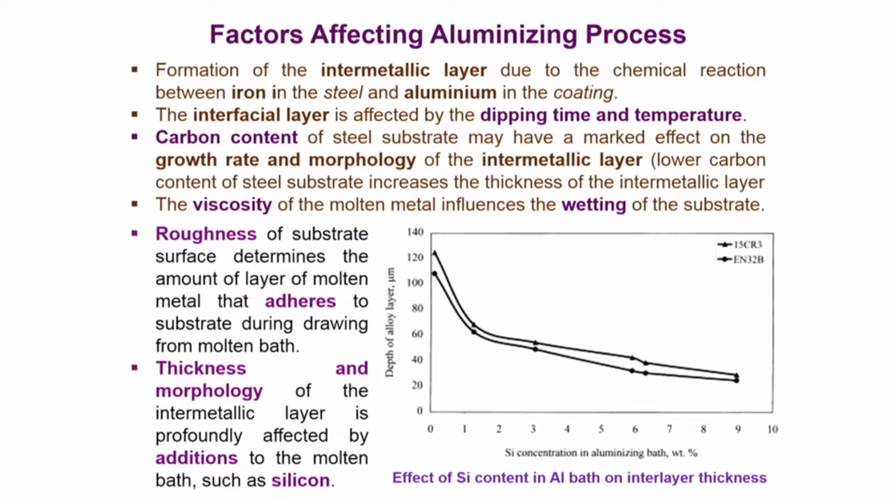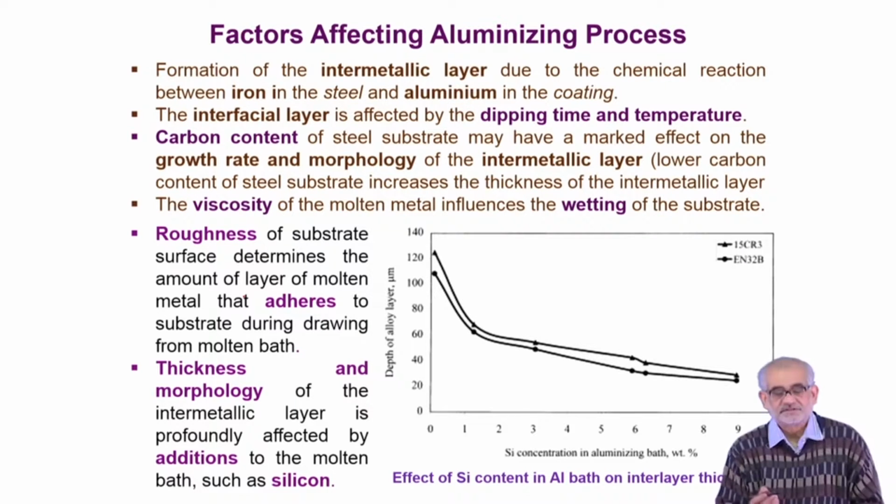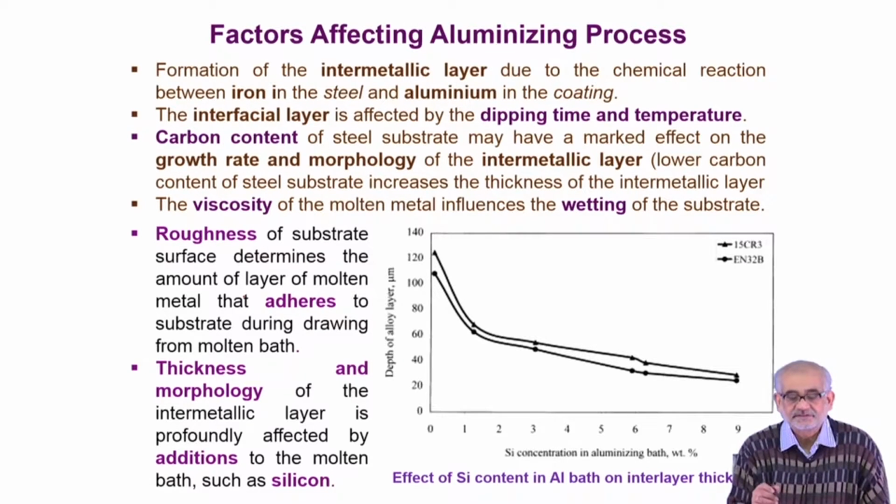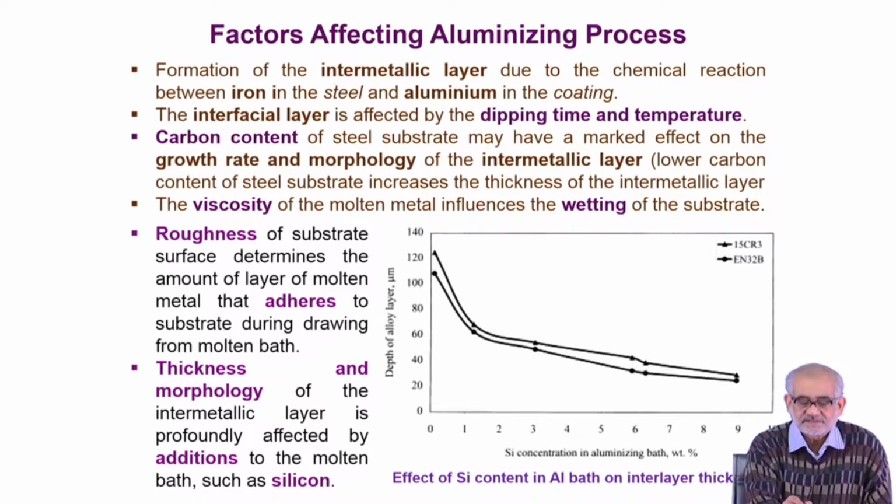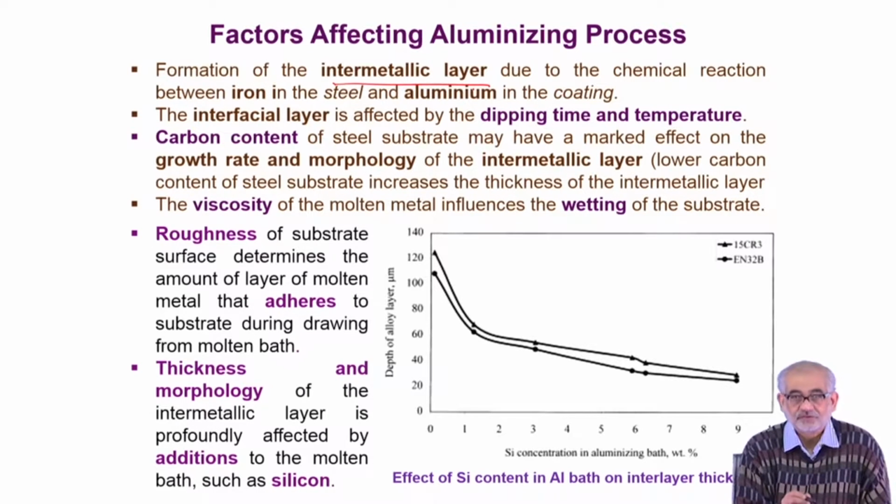There are multiple factors, process parameters, which actually affect the thickness and the integrity of this coating. As I said, this is an intermetallic layer that we form. So we have to be careful as to what is the time that we expose to, because otherwise the layer that you form will be extremely hard and protective, all right, but also is fairly brittle, and most importantly will have a very different crystal structure and coefficient of thermal expansion than the underlying metallic substrate.